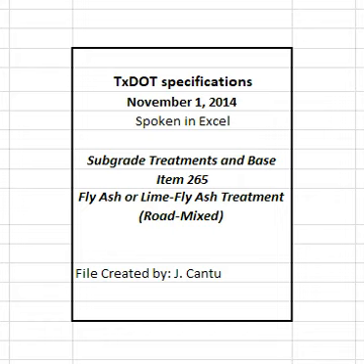Where subgrade is constructed under this contract, correction of soft spots in the subgrade or existing base will be at the contractor's expense. Where subgrade is not constructed under this contract, correction of soft spots in the subgrade or existing base will be in accordance with pertinent items or Article 4.4, Changes in the Work. Where subgrade to be treated under this contract has sulfates greater than 7,000 ppm, work will be paid for in accordance with Article 4.4, Changes in the Work.